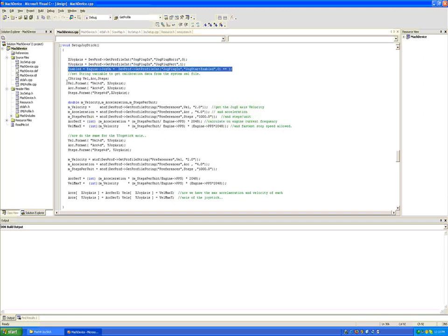Now you can see here, for example, I'm creating some C strings and getting variables by C string format. For example, the velocity of an axis is stored as vel0, vel1, vel2. So here I am creating a vel1 because xjoy axis is currently set to the x-axis. Therefore, I want the velocity of the x-axis, so I can set up velocity and acceleration variables. When you play with this, you'll find out how it's done.